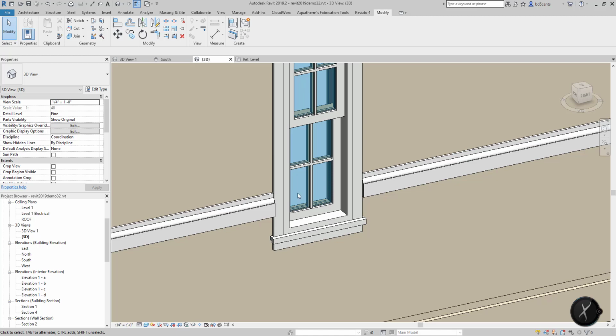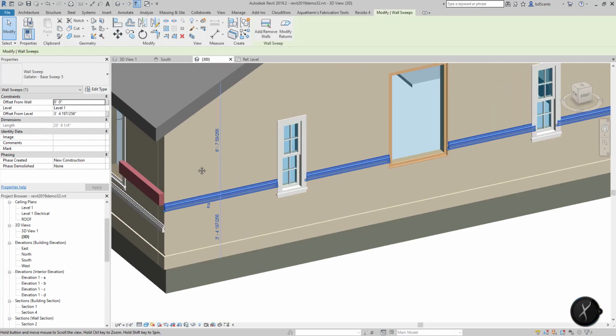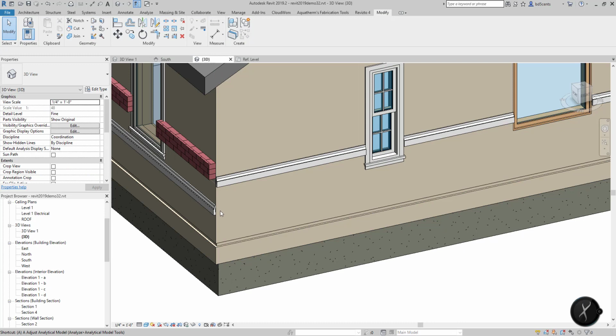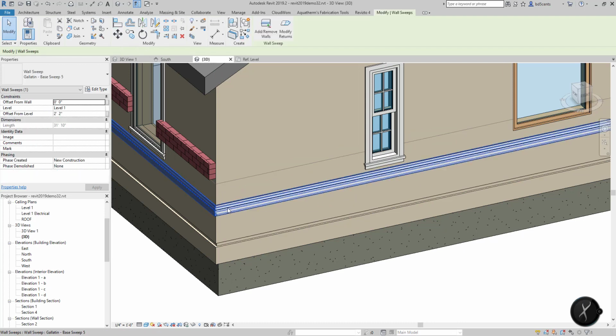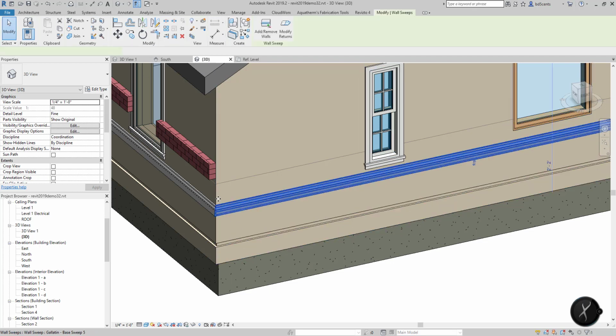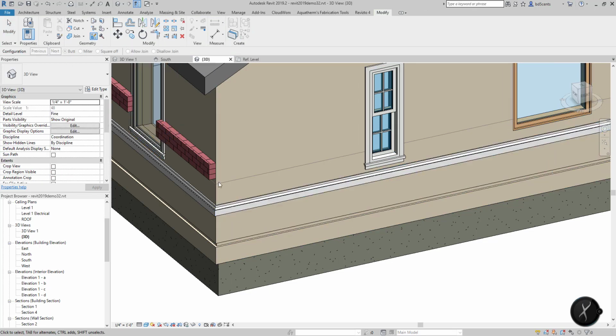From there, you can adjust whether they're mitered edges or butt edges, butt or miter, depending on how they're actually connected. Now in this case, I don't have them aligned correctly, so if I align the bottom to the bottom there, those are now adjusted accordingly. What we could do is edit the wall joins here. Oops, sorry, not there. Right here, and we could adjust what's happening to those based on how you're allowing the joins.